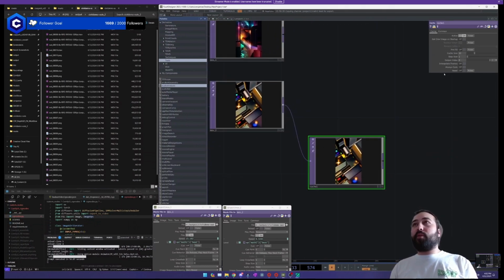And I'm going to use this to essentially delay the frame by 2 frames. So I'm going to change this output index parameter. One of the cool things about Touch is if you middle click on a parameter, it lets you change it like this. So you can change it by 10, or by 0.001, very easily using the middle click. But in this case, I'm just going to do -2.